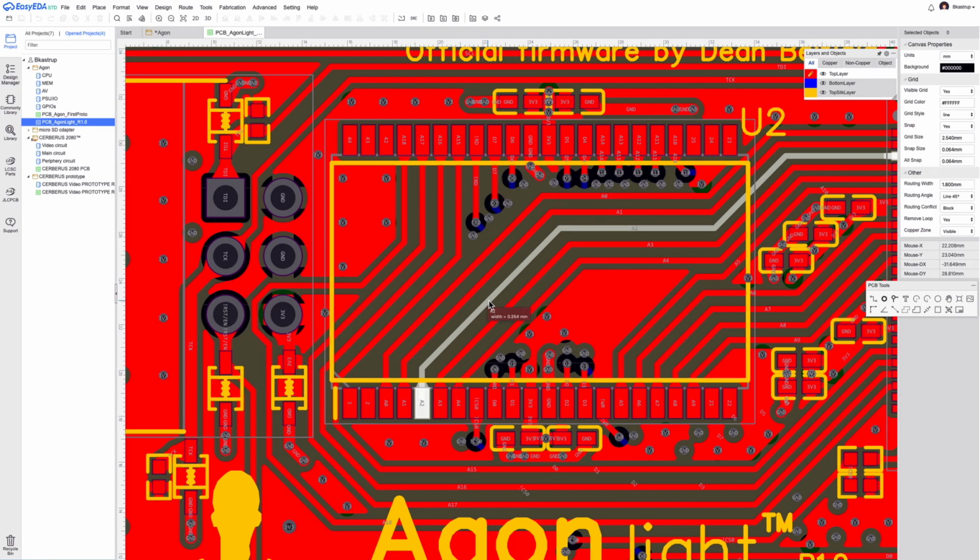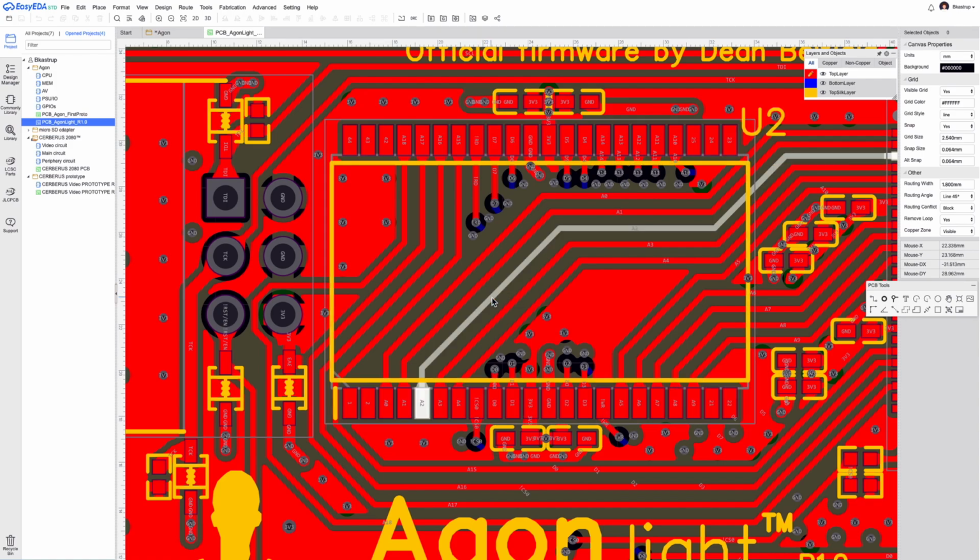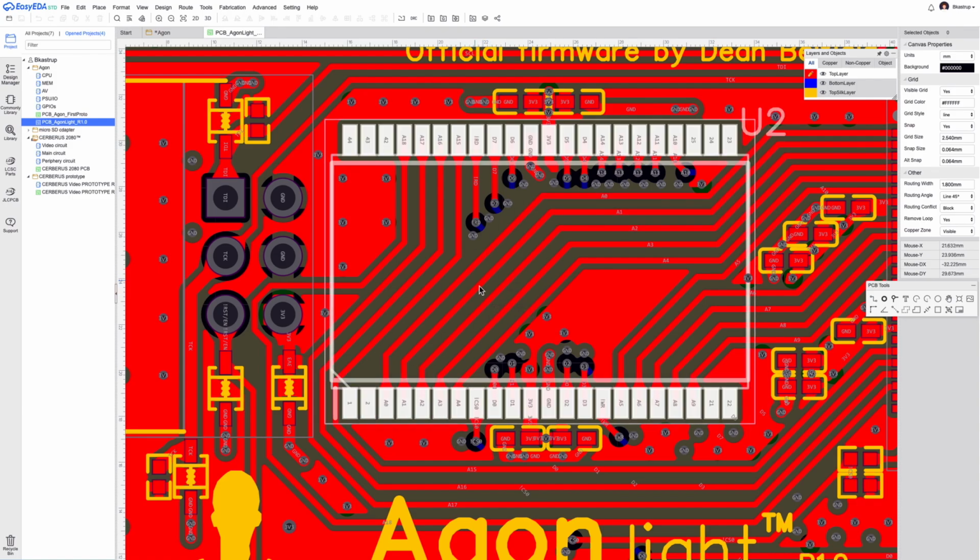Again, this idea: I see some hobbyists designing boards, and they like to keep the lines very neatly close together because it looks good. Well, do you want to make a board that works well, or do you want to make a board that looks good? If you want a board that works well, you keep non-differential lines, that are not part of a differential pair, as far apart as you can to prevent crosstalk.